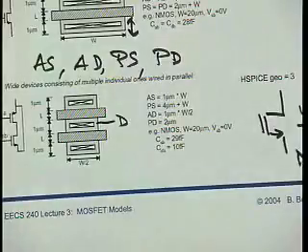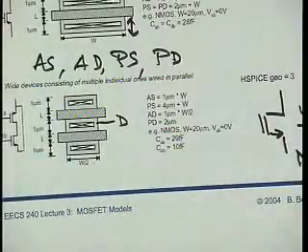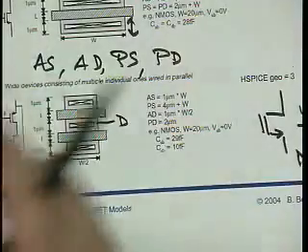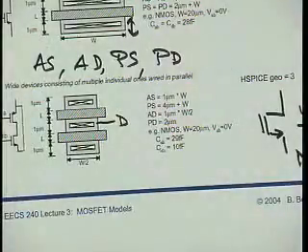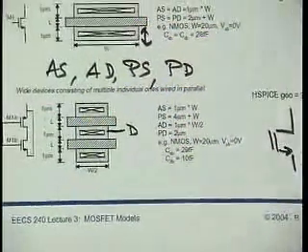Now, in HSPICE, there is a way to set this up so that it automatically calculates reasonable values. That may not be even too far off. In other versions of SPICE, like Spectre, you can make macros which take W and L and then calculate the right AS and so on from those, in addition to the W and L you've specified.